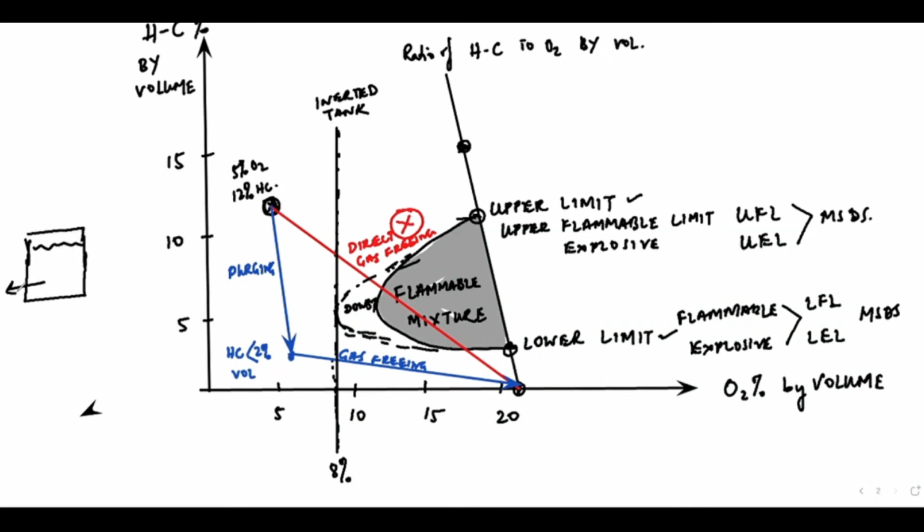Now this tank is closed, and on the top I have a piping which is bringing in IG. So from the bottom this pipe is going to remove the cargo, and before I start removing the cargo, I will start the IG system. It will keep on pushing inert gas into the tank, and then I will start the pump and I will start removing the cargo. Now I have to maintain minimum pressure in the tank. Yeah, minimum pressure must be maintained.